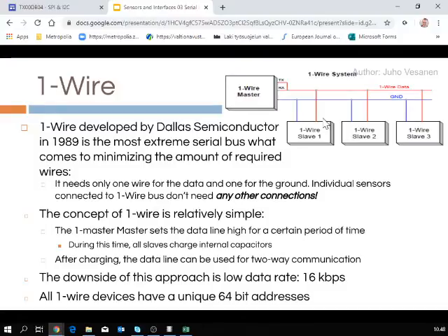These are typically very low power devices, and they can generate the power from the data line. They usually draw, say, in standby mode, less than 1 milliamp of current. So very low power devices. They usually also need a capacitor to act as a charge bank, but anyways, the bus itself is only one wire with branches. Okay, simple.